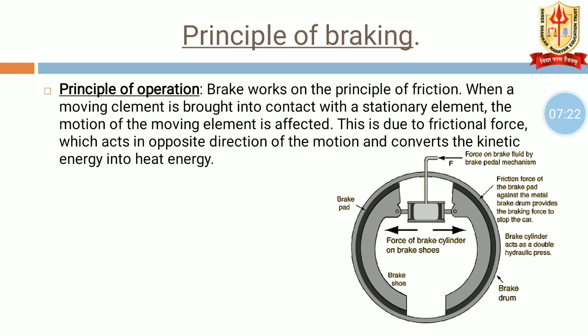Now the principle of braking. As we have discussed earlier, braking operates on friction. Brake works on the principle of friction. When a moving element is brought into contact with a stationary element, the motion of the moving element is affected. This is due to the frictional force, which acts in the opposite direction of the motion and converts the kinetic energy into heat energy. That's why heat is produced while braking. Now, what are the components? With the help of this diagram, we can understand the frictional forces.